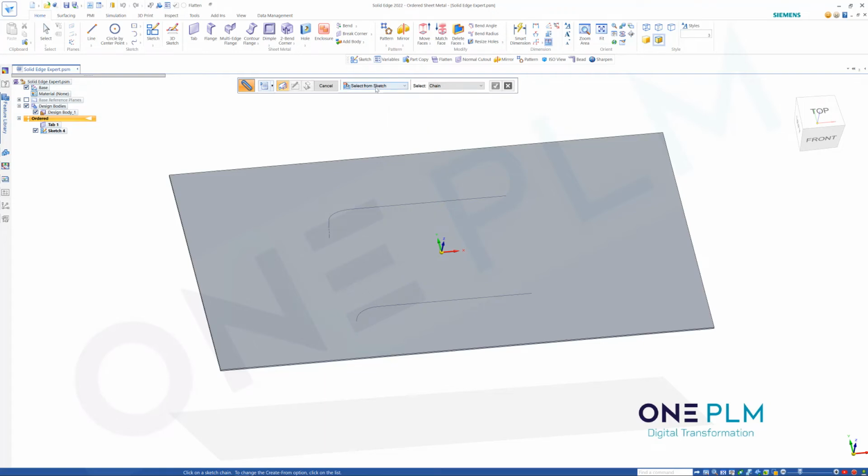So if we use the slot command, we can choose select from sketch on there. If you don't have this, the slot command is also available in this little toolbar as well. If you use the up and down keys, that will tend to switch between the different options on there. So that can be really useful. There are a lot of keyboard shortcuts that aren't always obvious.